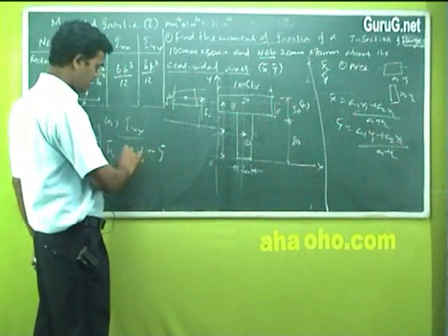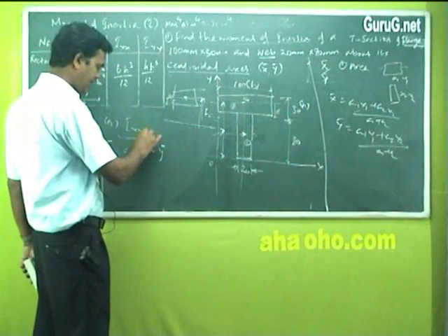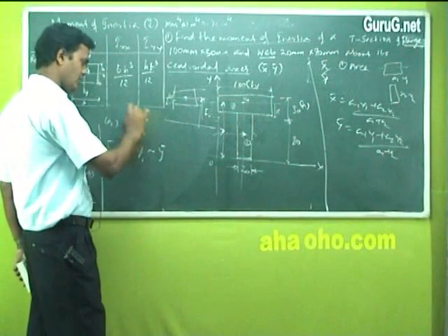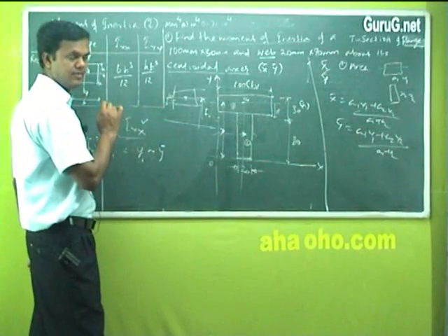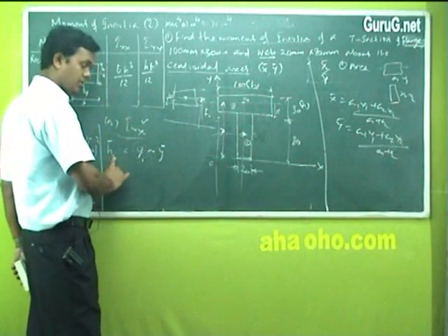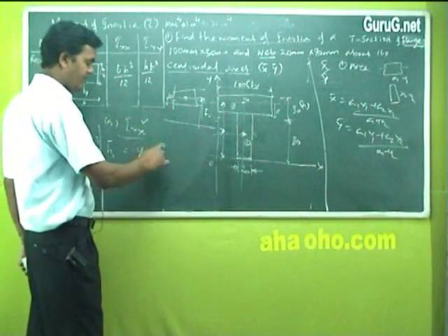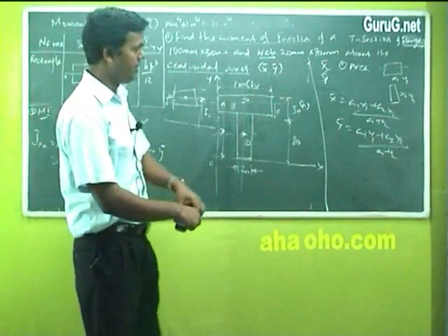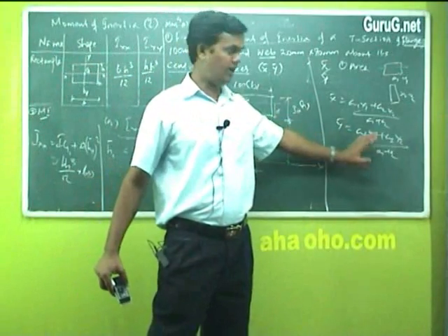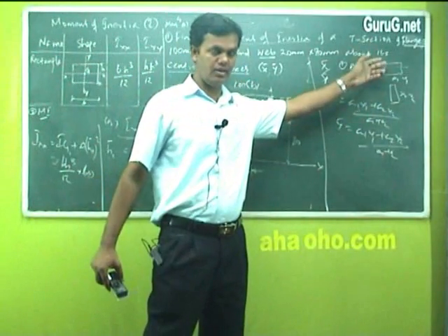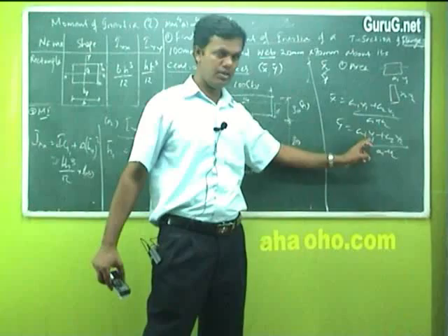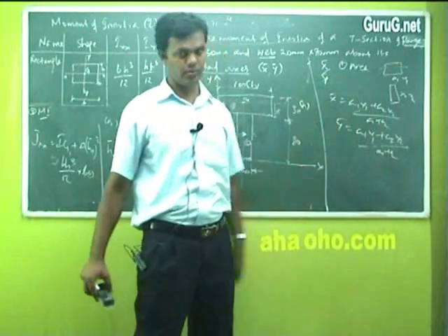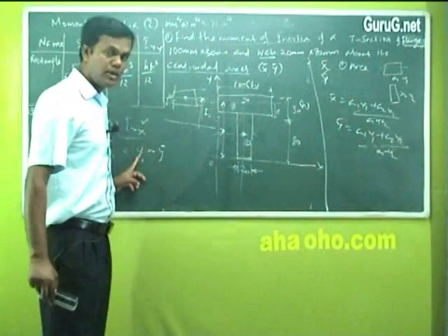Y1 means, for finding Ixx, while finding moment of inertia in the x direction, xx reference axis, to find H1 bar, you should take the difference of the value of Y1 and Y bar. Y bar is a constant value. After finding area etc., you will get Y1, Y bar. Suppose say here 40 millimeter is Y bar. Y1 is what?